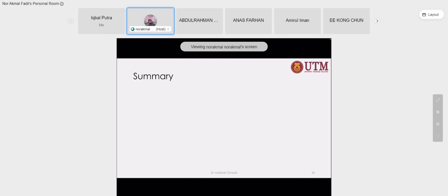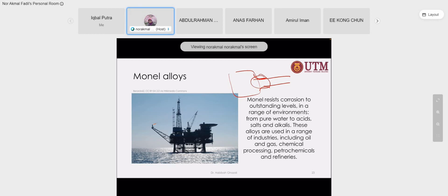Other than Monel, you can search for other famous nickel alloys such as Inconel. This one is a famous super material. We call it a super alloy. Expensive cars with a turbo, you always hear about turbo, right? Basically, it's driven by a turbocharger. Expensive cars sometimes use Inconel, the best material for the turbocharger part, so that it's stable at high temperature. It can minimize heat loss, so that it really utilizes the energy.